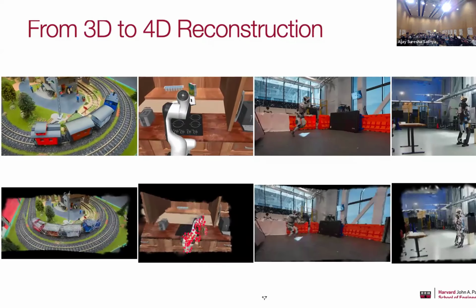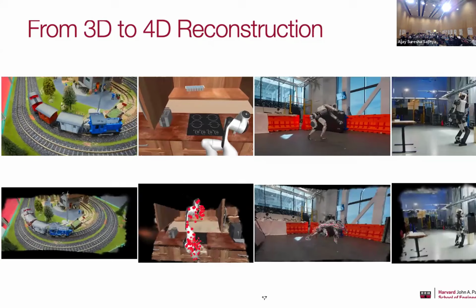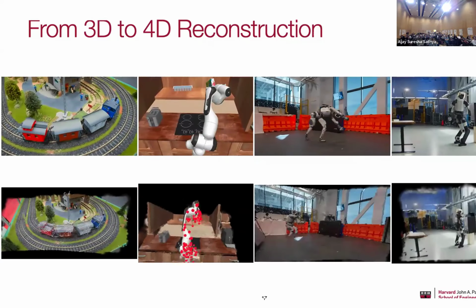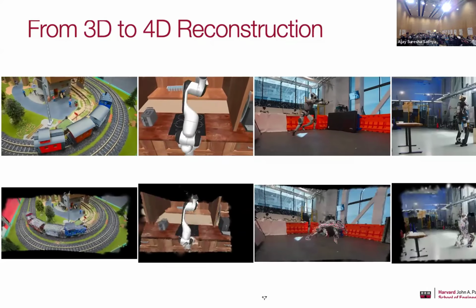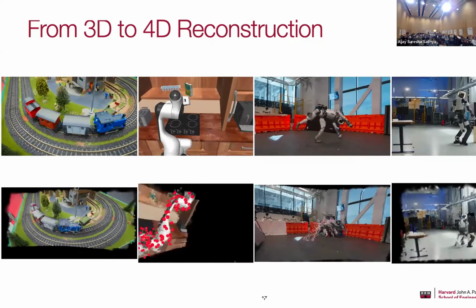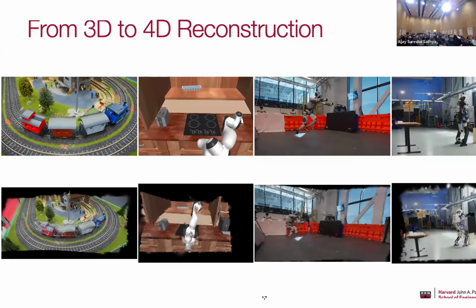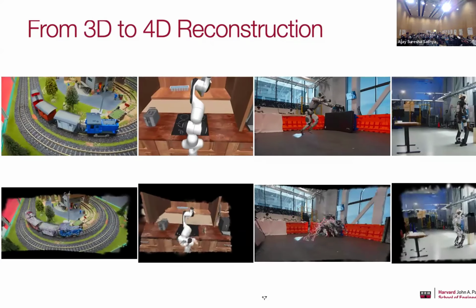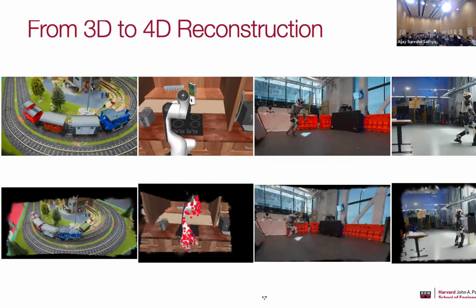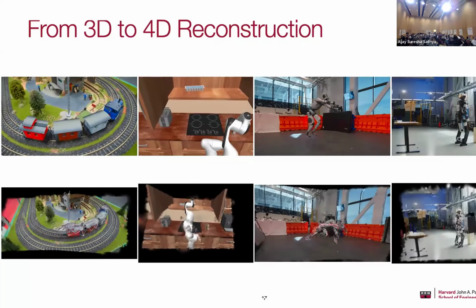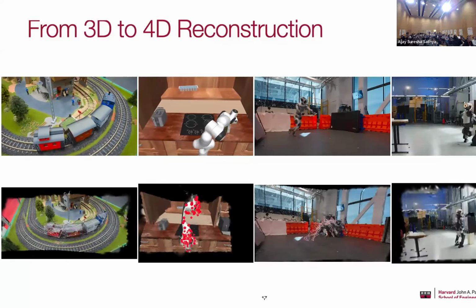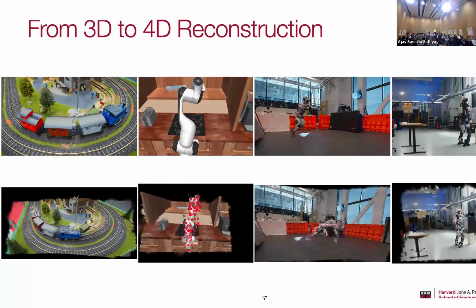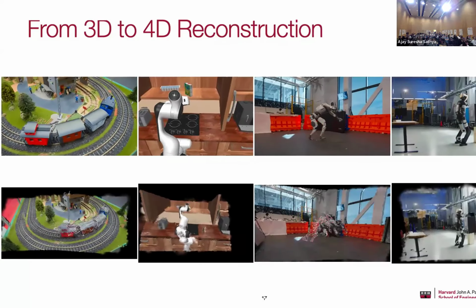So as you can see, the static part still follows the XM approach, but what we added here to accommodate the dynamic objects is something we call embedded deformation graphs. So basically, with these robots, because they are moving, you have this kind of wireframe, but they are deformable, and then you can reconstruct these wireframes using convex optimization exactly in the same way as we did, using a QCQP followed by a low-rank projection. And then you can do dynamic Gaussian rendering style things.